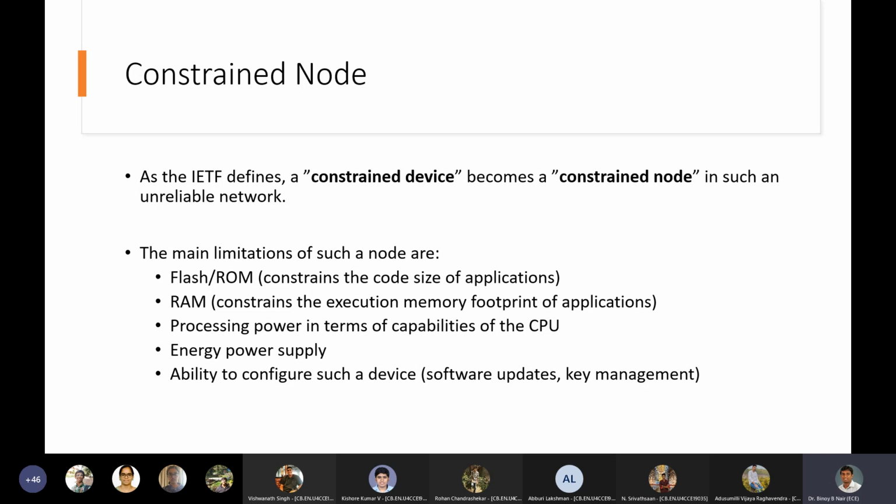The third problem that you will have is obviously the issue of processing power. Most of the boards that you will see now are classified based on what kind of processing power you need. You have separate boards which can do DSP processing, like the Texas Instruments TMS boards, which can do signal processing very nicely. There are several different ARM architectures now available, like the Cortex boards, which can have a lot of processing power. On the other hand, you have the smaller architectures, typically simple RISC architectures, which can be used for smaller applications like your Arduino Uno, and so on.